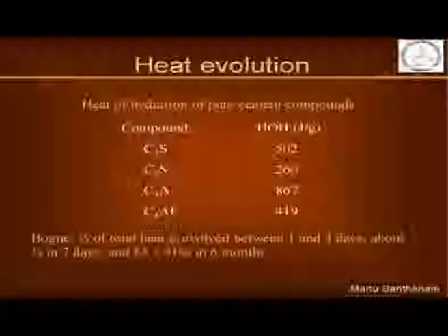Please remember, we had talked about general principles of cement classification. I said that when you want to lower the heat of hydration, you need to increase the C2S content and reduce the C3S content, and that is exactly what is seen here. We see that with C2S, the extent of heat release is minimal as opposed to C3S or C3A.